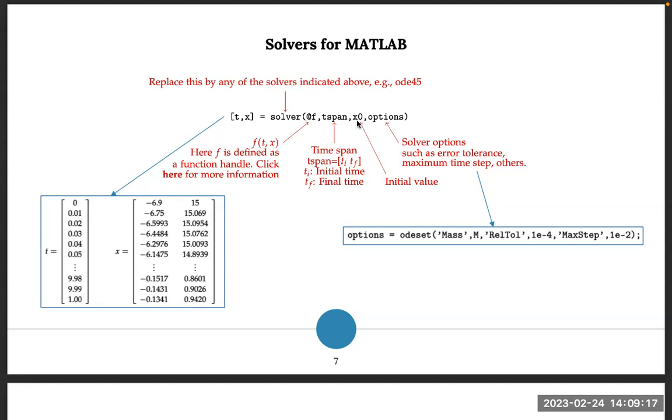You have to solve a power flow, so you get the steady state of the system, you get how the variables are in a steady state, and you use that solution of the power flow as your initial condition. That's the general procedure. Of course, you're going to study that throughout the course, but it's important to know that it's different than any other system. Generally, you can assume any initial condition, and you have your dynamics, and you see how the dynamic evolution of the variables is going to be. But here, we have to be very careful and start from the power flow solution.